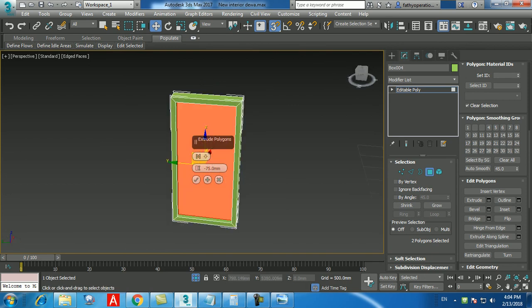Normally the door thickness is 45. 50 mm is the leaf thickness. But here we need to adjust it on any face, external or internal face. It is not coming in the middle. Currently it will come in the middle. Yeah, now it's in the middle. Yeah, we need to place it on the internal face. Thickness is currently 50, that is okay.